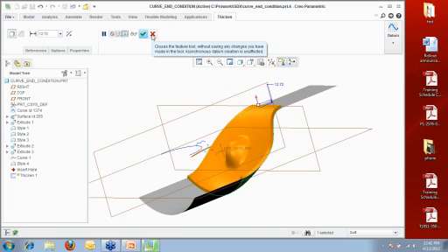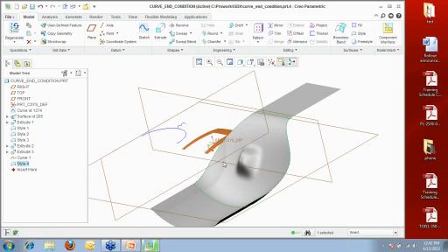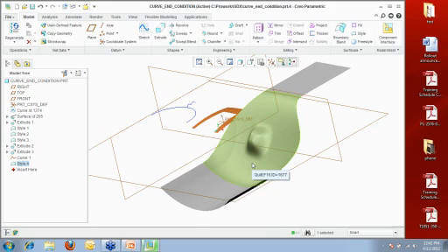So for the most part, this is kind of the concept behind what ISDX gives you. You use ISDX not as a standalone tool. Can you? Yes. But in most cases, you're using it in conjunction with some of the other things you can do. We connected this surface onto parametric models, or parametric surfaces. So this was done with just an extrude. This guy was done with just an extrude. I merge everything together, give it a thickness, and all I have is one feature, an ISDX feature, that's attached to my other objects that are parametric features.